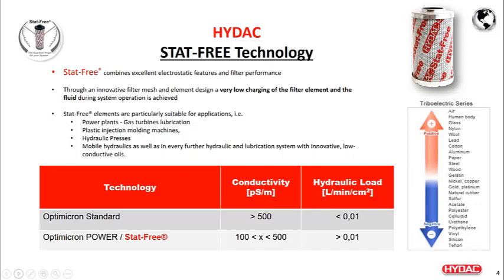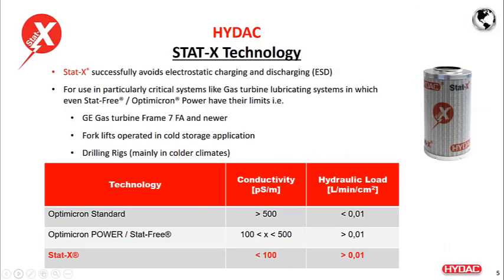But as we got more and more into this technology and more oils getting refined, a concept called gas to liquid came into place. And what is that gas to liquid phase? Basically, it's a synthetic type of oils. They are also very highly refined and also exhibit very low conductivity, as low as 2 to 3 picosiemens per meter at normal room temperature. And having such a low conductivity, HYDAC got more experience working in these type of applications and developed another technology, StatX media.